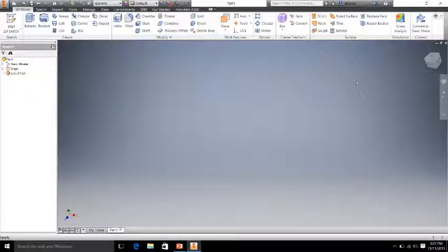So if we go back up to the right hand corner in this little cube, you see it says top, it says front, it says right, and it says click or drag. So if we just click on the right side, it's going to automatically bring our view to our right side view. And if you look down here on the left, now we can see our Z, our X is the red that's coming right at us, and our Y is the green that's still facing up. So if we want to, we can go through and sequence through some of these buttons.